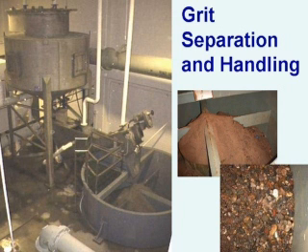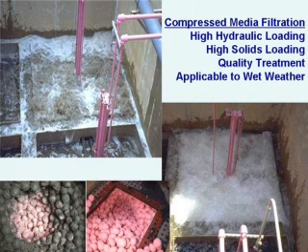These facilities in Columbus have a flow meter and pinch valve that regulates the flow to the vortex separator. And that flow meter and that pinch valve is what causes the controls to let the vessels fill up and then go online and restrict the flow to those units. And that flow information is sent to our chemical metering pumps that meter in the chlorine and the dechlorination parts of the treatment process. The underflow from the vortexes is pumped to another vortex grit separation device, and this is where all the maintenance is.